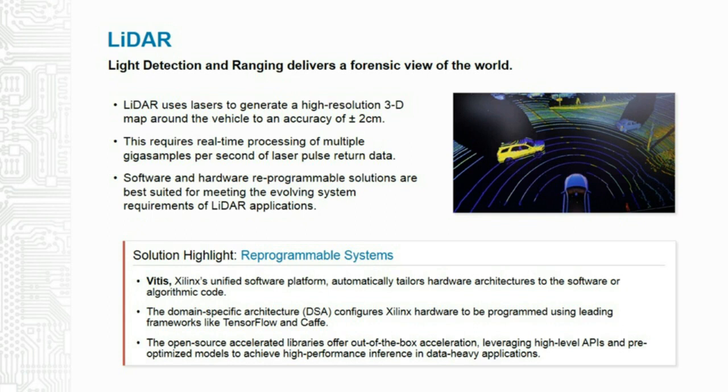It enables a self-driving car to have 360-degree visibility and accurate depth information to an accuracy of plus or minus 2 centimeters. It can detect the exact size of an object and identify details in an object from a few centimeters distance to more than 100 meters distance. It works well in all light conditions and is unaffected at night. Performance does drop a little bit in snow, fog, and rain, but it doesn't drop as much as a camera system will in the same conditions.